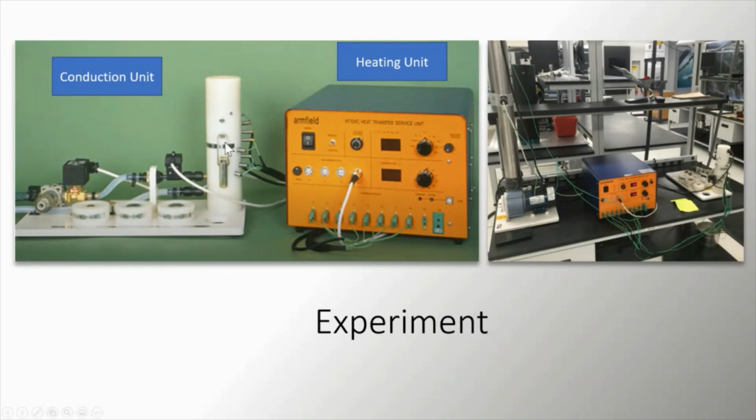So what we're going to do, we're going to put this in the middle section, and we're going to calculate the heat transfer, and calculate the temperature difference, and from there we're going to find out what conductivity this specific metal has, and from there we're going to find out what metal it is. These extruded things are your thermocouples. They are connected in here, so this screen will tell you which thermocouple has what value. You have 10 thermocouples in total, but only 4 and 5 are the thermocouples that are going to get into that unknown material.